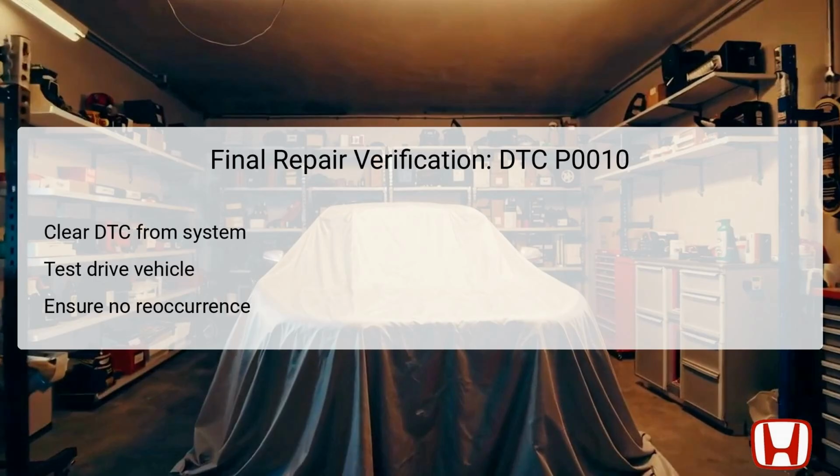Next, a test drive should be performed under various conditions to ensure that the engine operates smoothly without any performance glitches, and that no warning lights reappear on the dashboard. Monitoring the vehicle during this test is vital to confirm that previous symptoms have vanished and the repairs are functioning effectively. If DTC P0010 does not return after this test, it can then be concluded that the repair process has